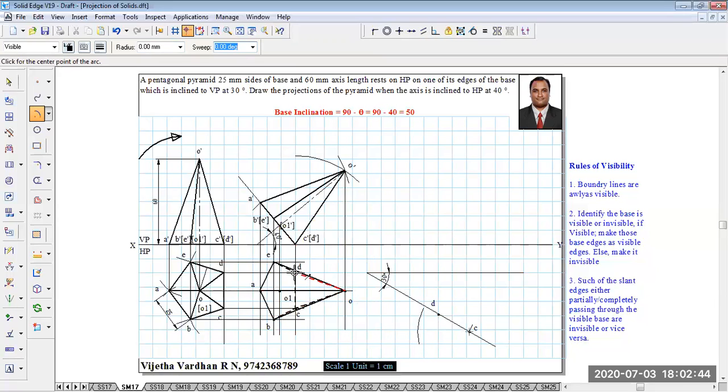And then I'm going to measure the same distance E from D now. Now, using the compass, I'm going to measure this value, and then with D as the center, I'm going to take the same radius and draw an arc. Now, the intersection that I get there is called the corner E. Now, using your pencil, you can mark it as corner E.